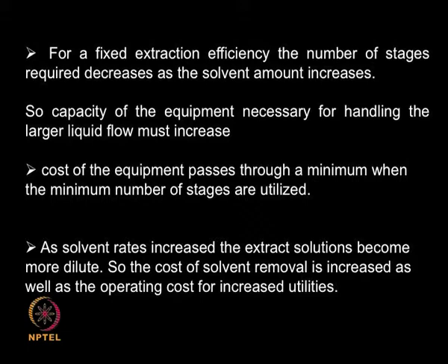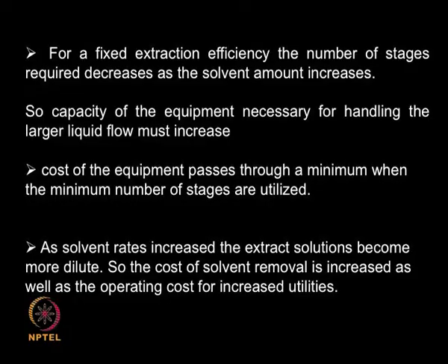But then if I am going to have fewer stages and more solvent, obviously the size of the stage has to be sufficient for handling so much of the liquid. So, each stage may be of very big size. So, you see the advantage of reducing the number of stages is balanced by an increase in the size of the stage. When I have a larger sized stage, the cost increases, but I may have fewer stages. So, you need to find out which is more efficient.